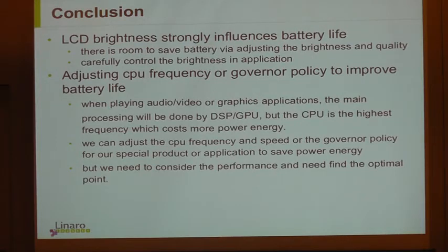Okay, here are the conclusions we get from the above test case. First, the LCD brightness strongly influences the battery life. The second is we can improve the battery life by adjusting the CPU frequency or governor policy. And with this method, like I said before, we need to consider the performance.